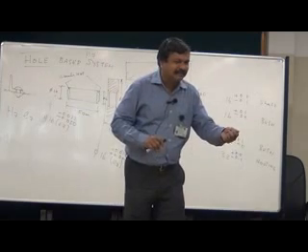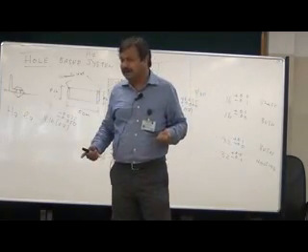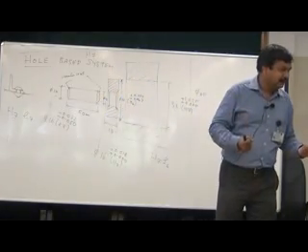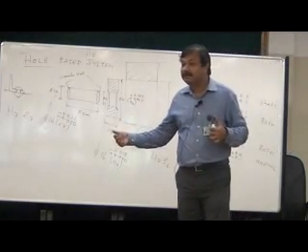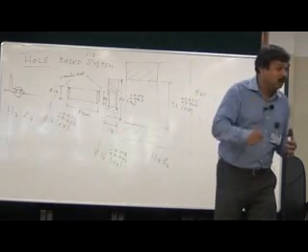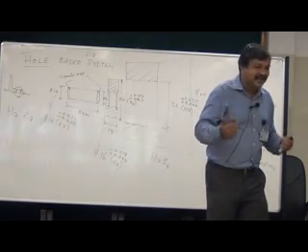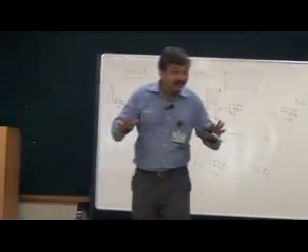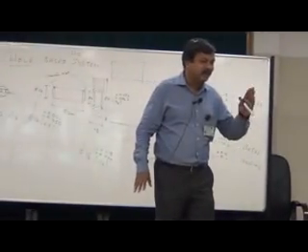Why should it be so sensitive? Even if there is a slight change in temperature, why should it be underburnt or overburnt? Why doesn't the whole process become more robust, so that the variation in temperature will be there, but I'll still be getting good bricks? What is the logic? The logic is, if I design my process in a robust fashion, the whole problem can be solved in an easier fashion, in a cheaper fashion, rather than resorting to expensive solutions.